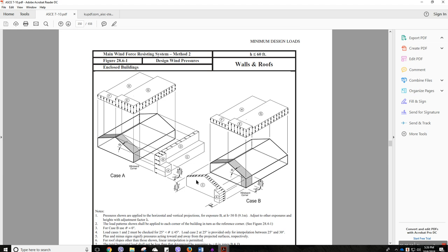So in our case, good luck for us, we're going to have an inclined roof, so you don't need to do any calculations or any application of the wind load on that one. We are going to apply the A load up to the total height, and C load, E, F, G, H. So for this distance, this is 2A. We need to calculate this one.